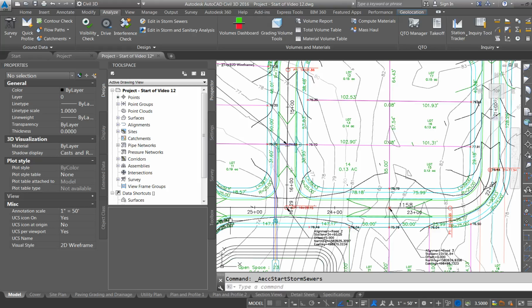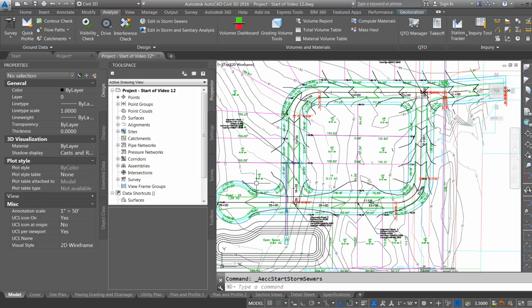Now, you can figure out the pipe sizes. I'll do a video on that for the hydrology and hydraulics class, and I may upload it here, I may not. But we're going to be using the rational method for designing the pipes. Now, that's all inside of Civil 3D.